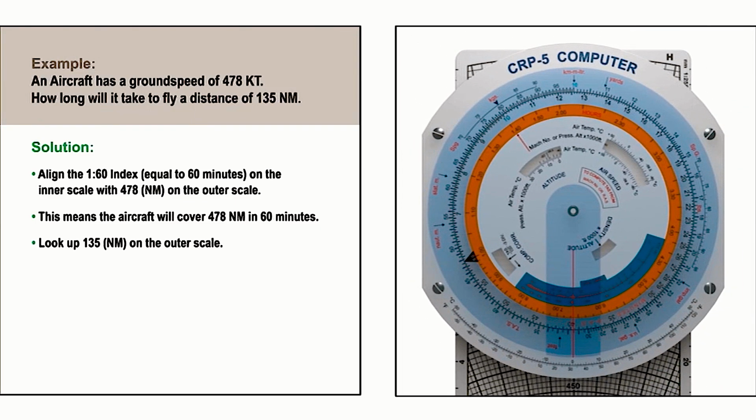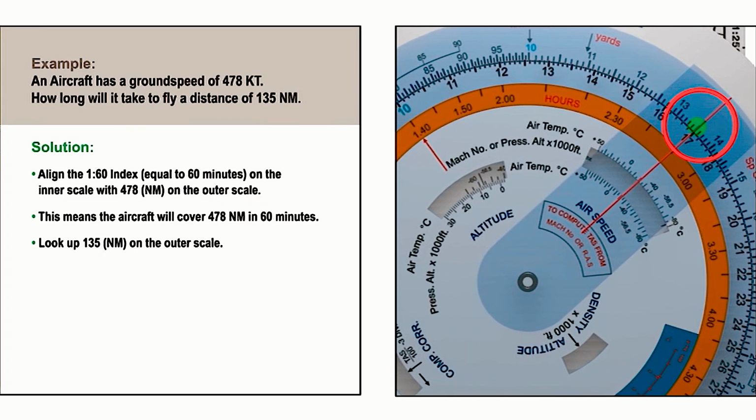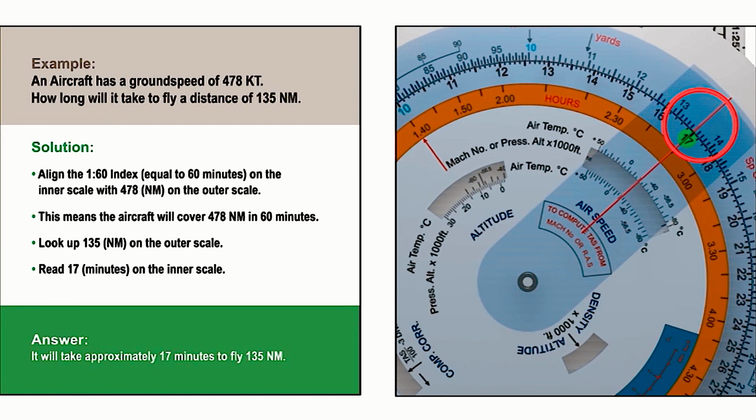Now look up 135 nautical miles on the outer scale and read across to 17 minutes on the inner scale. Therefore, it will take approximately 17 minutes to fly 135 nautical miles.